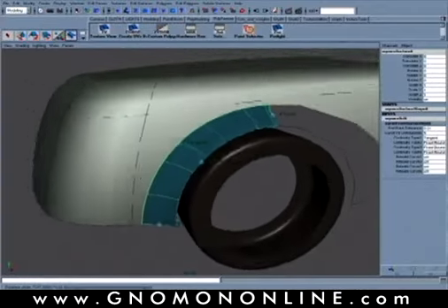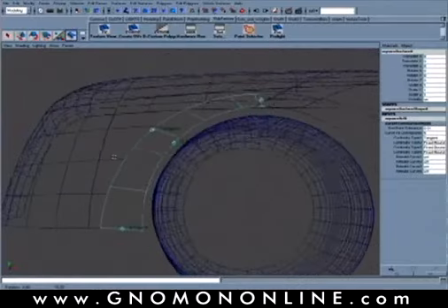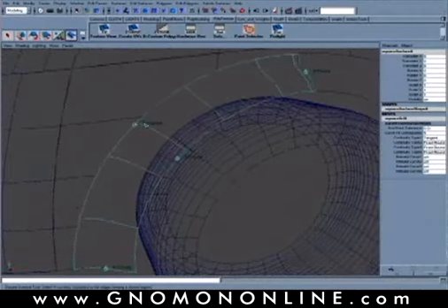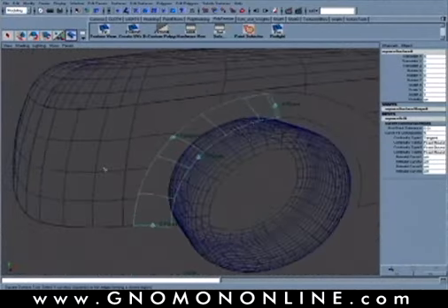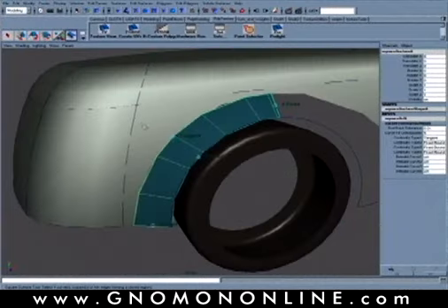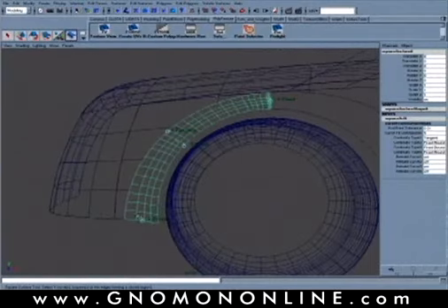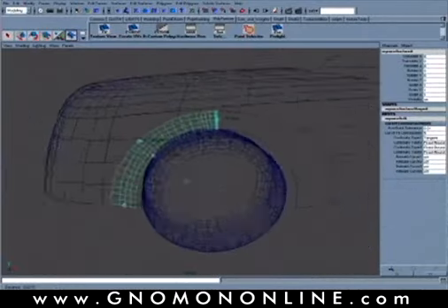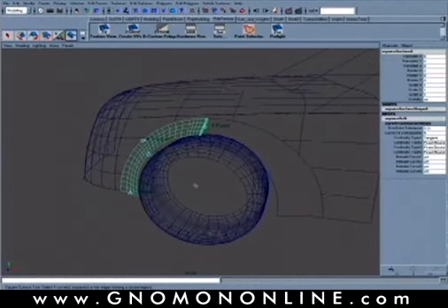Basically the setup or the way Square is going to get read in then, if we look at the green indicator lines that are here, surface number 1 here is automatically labeled tangent because it is sitting or butting up against another surface here. So we have these 2 connected. The other ones are all labeled fixed because there is no adjacent surface being built here. So the bottom edge, the rim profile, and then that section over there are all fixed. Okay, if we want to come back later and manipulate this, we can, but I'm going to go in and add in my other surface now.